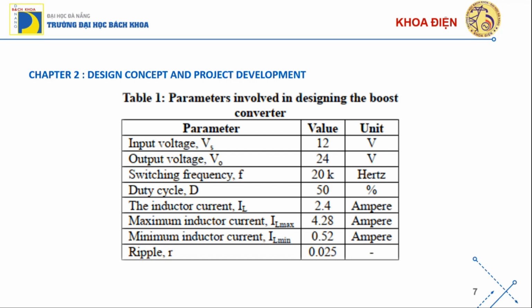Table 1 presents our case design parameters. We use a 12 volt input to achieve a 24 volt output with a 20 kilohertz switching frequency and 50% duty cycle.